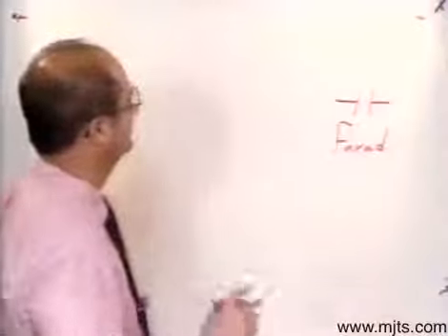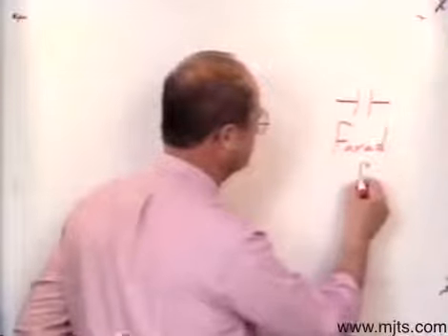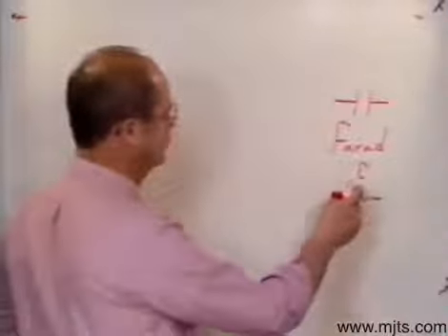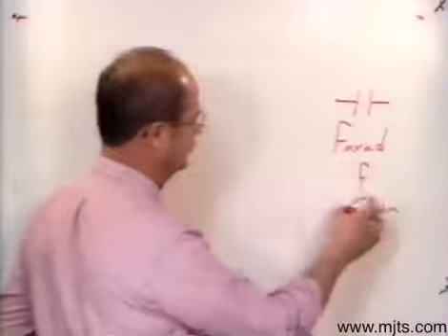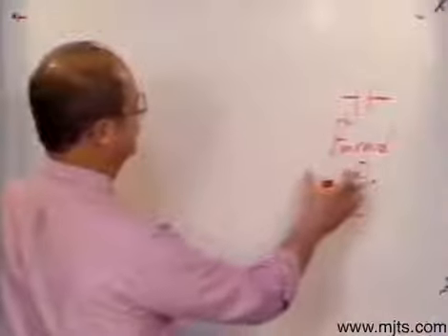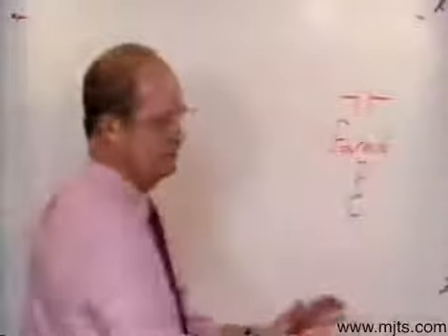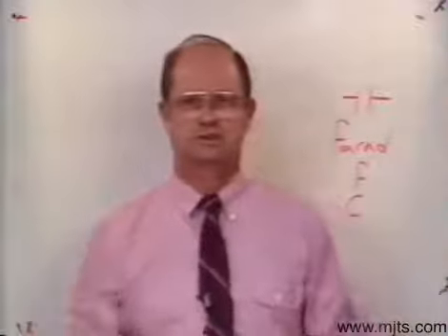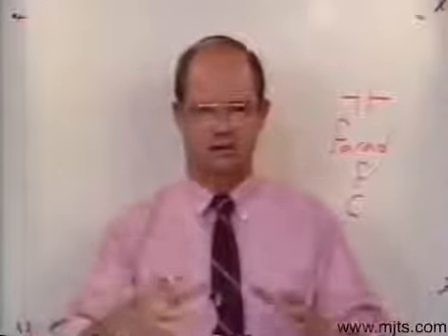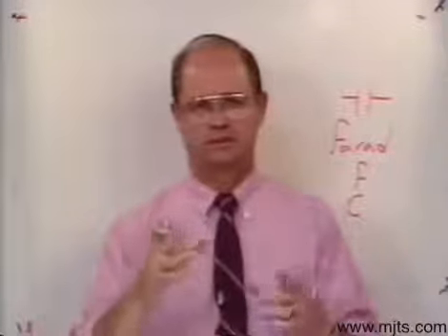Okay. Now, a farad, we'll use F for a farad. The symbol for a capacitor will be a C. We said R is a resistor, L was an inductor, C is going to be a capacitor. This unit of measure of capacitance is ridiculously high, you might say. In other words, a farad is a tremendous size. So in most cases, anytime I mention a value for a capacitor, we're going to be using prefixes.